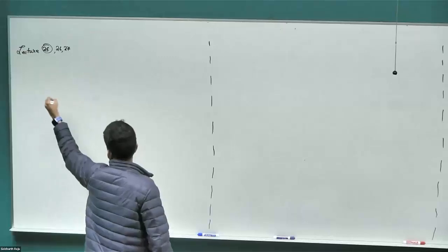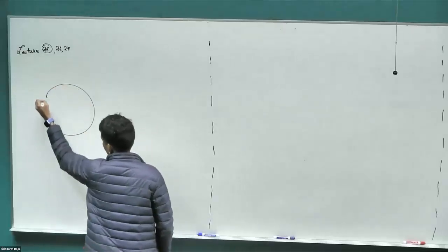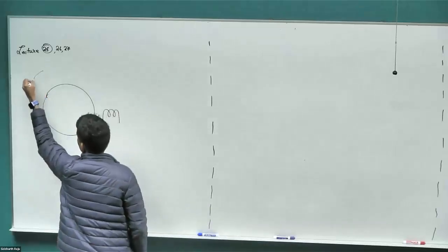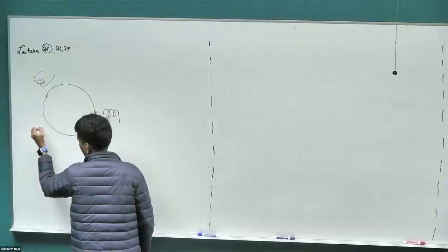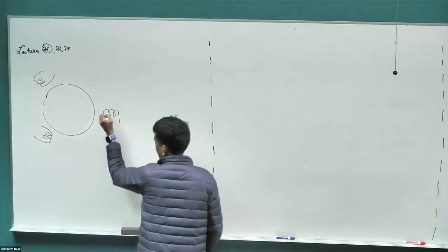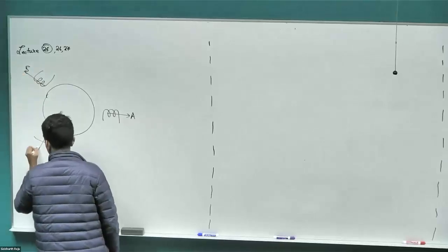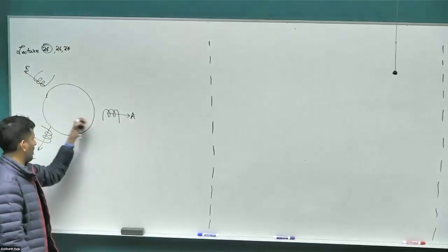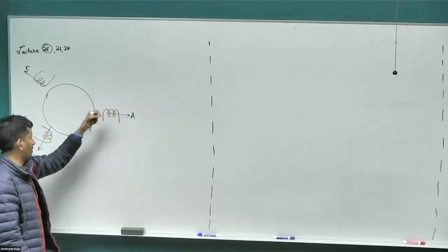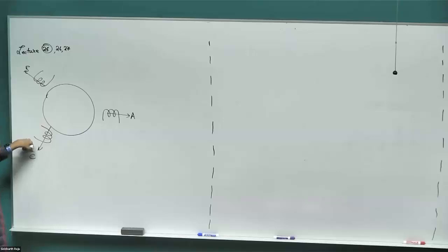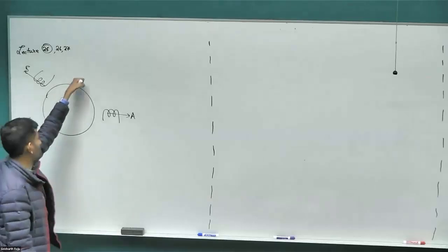So what we saw so far, that we have a stator, we have sinusoidally distributed windings, which are phase shifted by 120 degrees. So when I draw this diagram, the B field of the A phase is maximum along this direction. B field of the B phase is along this direction with its maxima. B field of the C phase is along this direction with its maxima. And then it's sinusoidally distributed everywhere else, right? So the positive maxima is here, negative maxima is there.